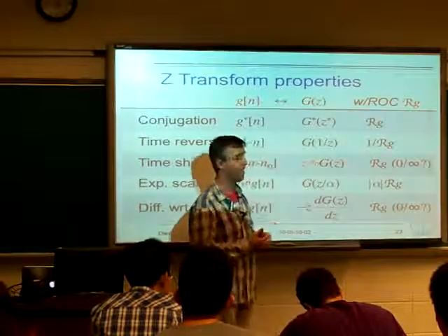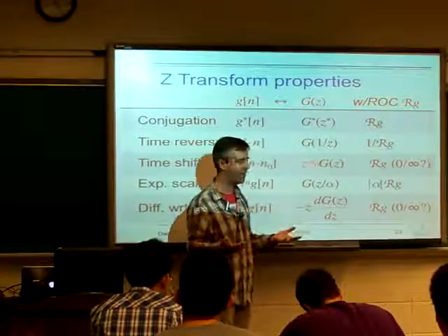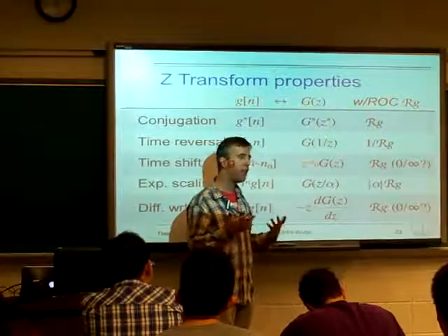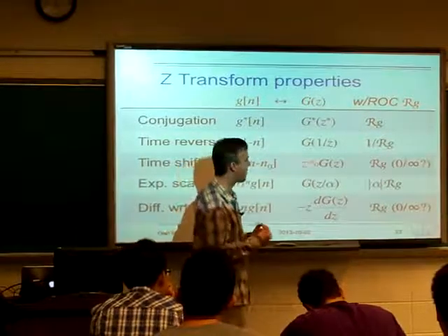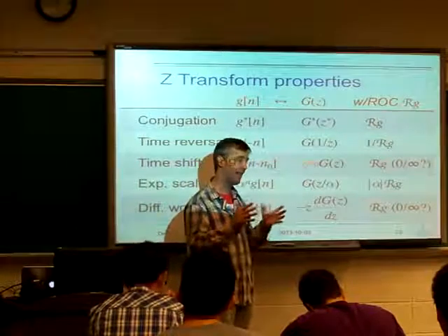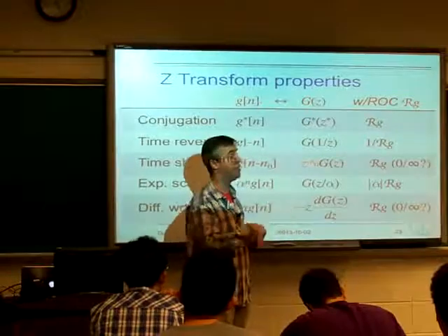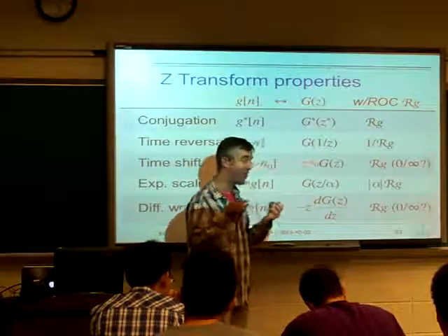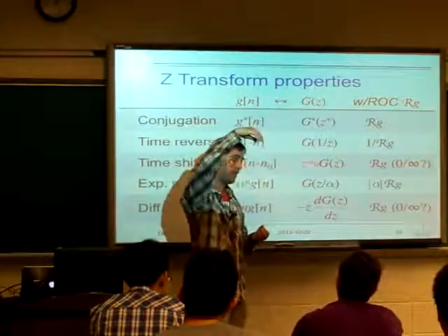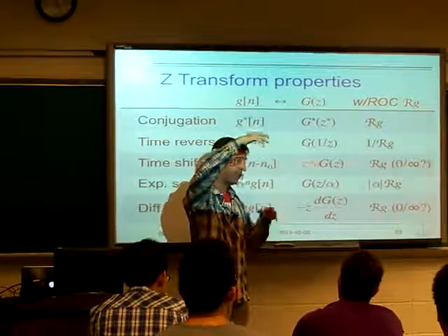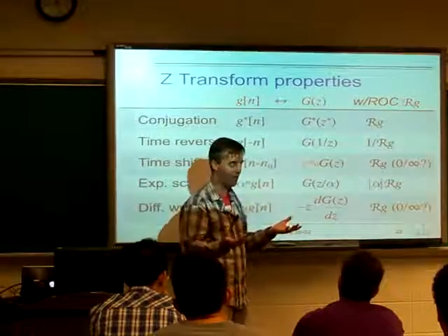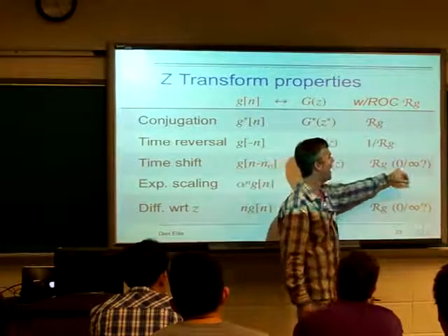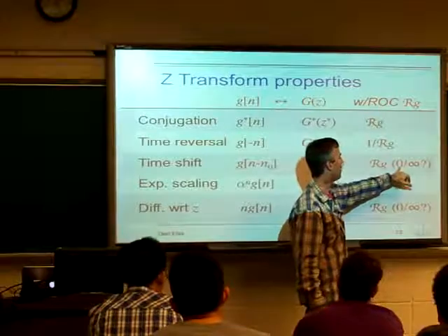You multiply it by z, and then you evaluate it, and it had some finite value at z equals infinity before, and then you multiply it by z. Now it's going to take on an infinite value at z equals infinity. Convergence means that the value is not infinite. And so if we have some expression, even if it's maybe not so dramatically ill-behaved as the ones we saw in MATLAB, if it evaluates to something that's infinite, then that does not count as convergence. And so that's why the region of convergence can never include these poles, because a closed form expression goes to infinity at a pole. It's got 1 over 0 somewhere in it, which means that, well, that's not converging. So that's always outside the region of convergence. So anyway, the region of convergence may differ in whether it includes 0 or infinity.